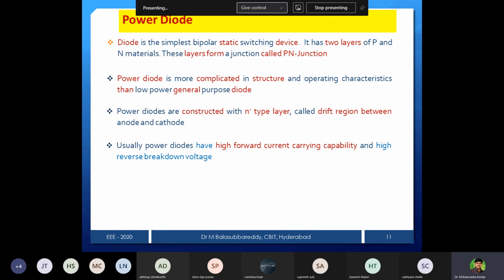Only whenever you require it should it be on. Because of the circuit operation, some other device may be conducting, and that voltage may be applied across this device and may be higher than the breakover voltage, so the device is automatically triggered. But at that instant we don't want to trigger the device.